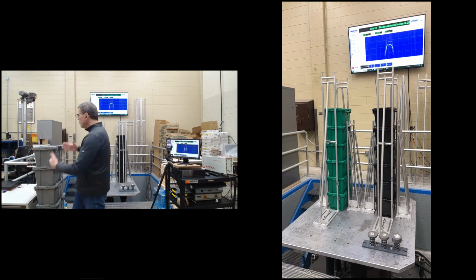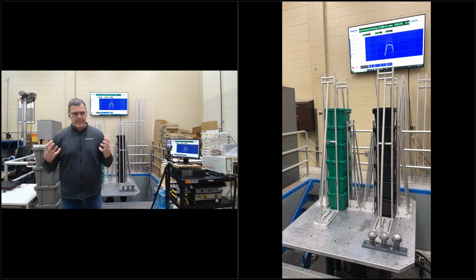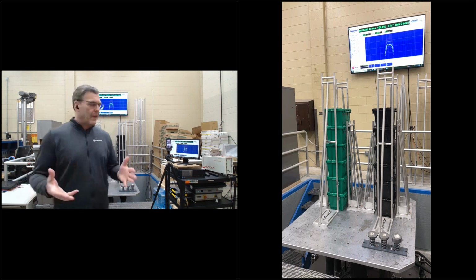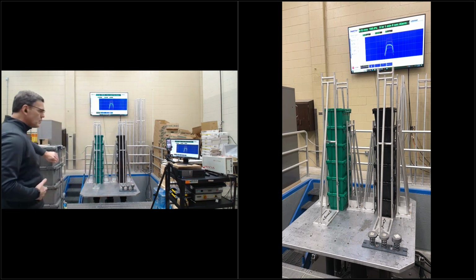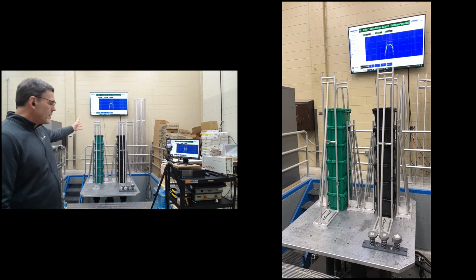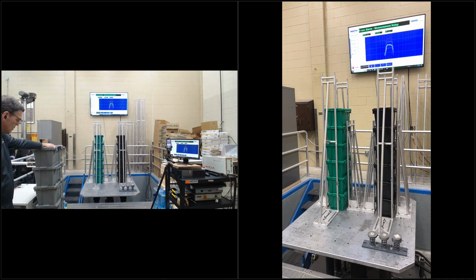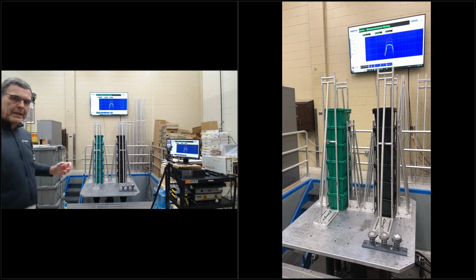And so when you unitize a load together like this or on a pallet load, it becomes a big, heavy mass. It's different than an individual one of these guys, or individual ones in a column stack where they're not bound together. The natural frequency of this unitized load is very low because it's one big mass.